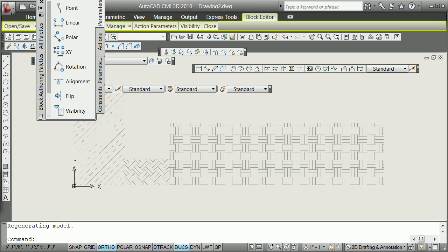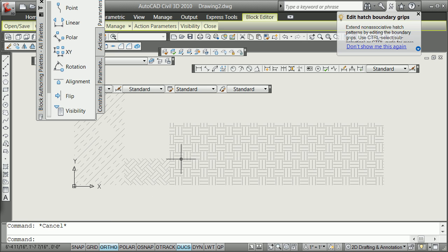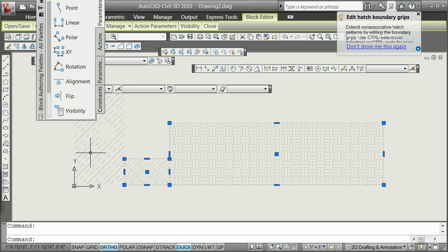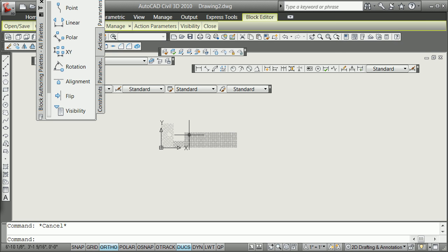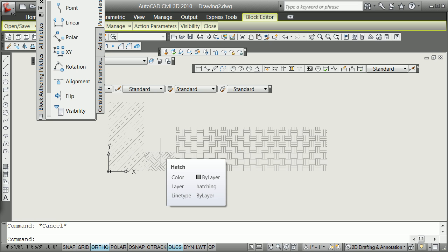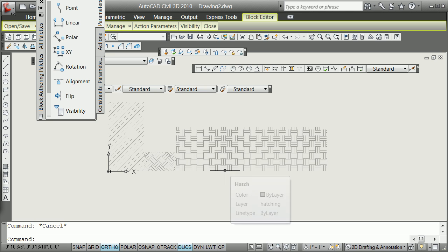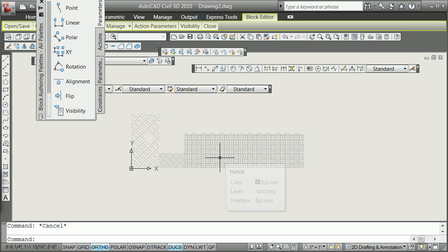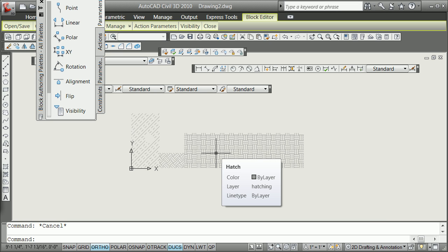Here's a new tip for you. If you're not going to explode dimensions, do not explode hatches. It will get to be a mess. But right in that, you can see that you can kind of come up with some nice information that, again, could be useful as much for sending out to other programs in a nice 2D graphic mode as it is within the 3D. You'll see a lot of this becomes a little bit more dynamic when you get into this kind of 3D world where you're cutting sections. Usually you'll see hatching when you do a section view. And I believe pretty much, like I've told you before, there's a fair bit of ability within some of these programs to do these sections actively. Let the program do it. So that's the use of hatch.